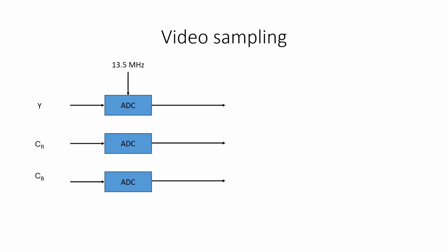The luminance signal carries the most detail, as was explained in the How Analog Color TV Works video. For standard definition pictures, the maximum frequency is about 6 MHz. This needs to be sampled at a frequency greater than or equal to twice per cycle, so a sample rate of 13.5 MHz is used to capture all the detail.